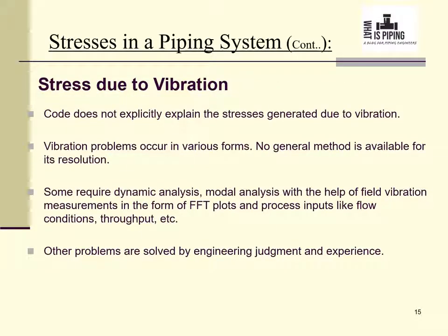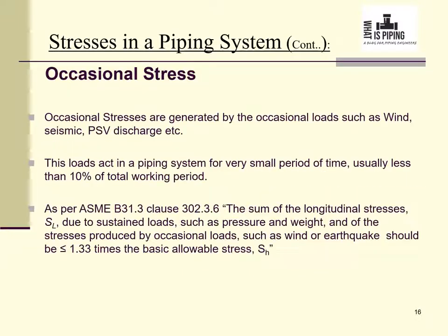Now stresses due to vibration. Code does not explicitly explain the stresses generated due to vibration, and vibration can occur in various forms. That's why no general method is available for its resolution. Some may require dynamic analysis, modal analysis. Some may require field vibration measurements in the form of FFT plots or fast Fourier transform plots. Even process inputs like flow conditions, throughput, etc. are required to solve vibration problems. These are normally solved by engineering judgment and from experience.